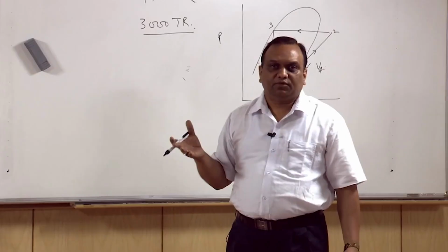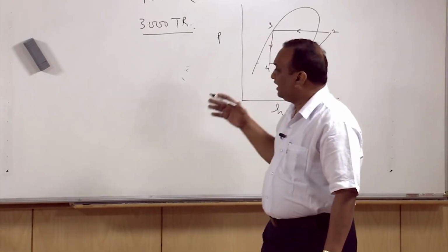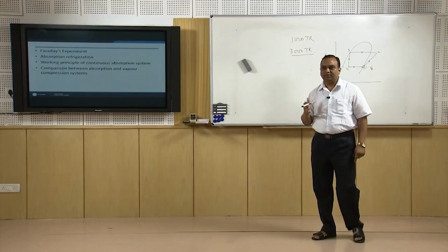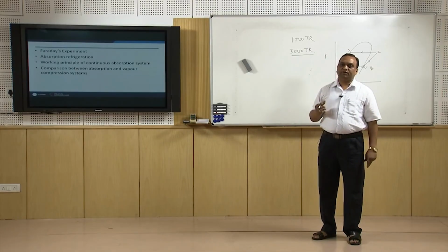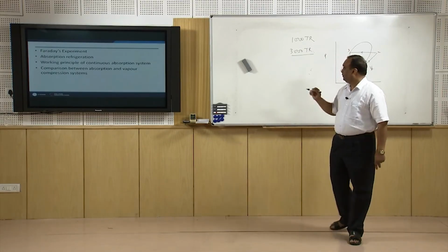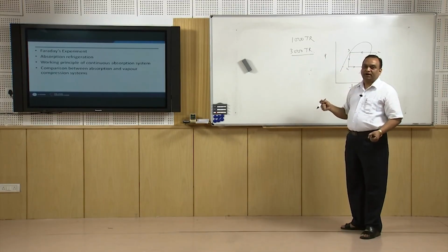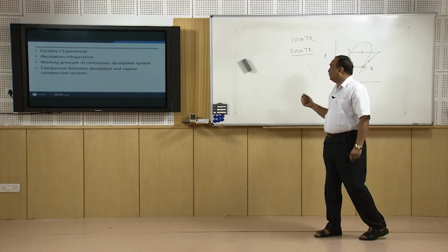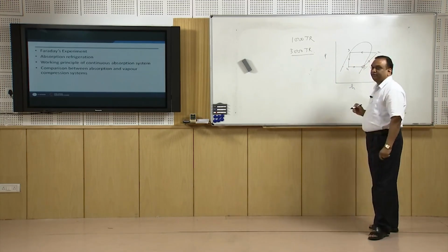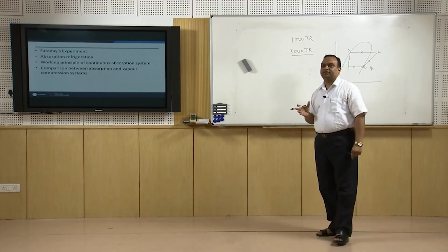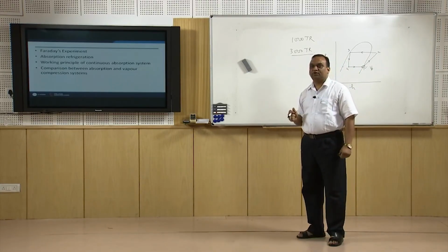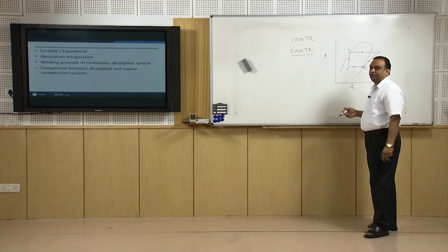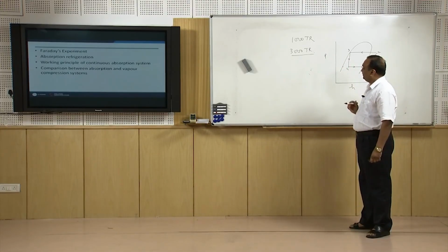Suppose I am using a reciprocating compressor. In that case, reciprocating machines are not fully balanced. Some unbalanced force will be there that will create the vibrations. Strong foundations will be required. In addition to that, to handle large volumes, rotary compressors are normally used. So, rotary compressors will also require very strong foundation. Size of the compressor will be very large, and the cost of this plant will also be high.